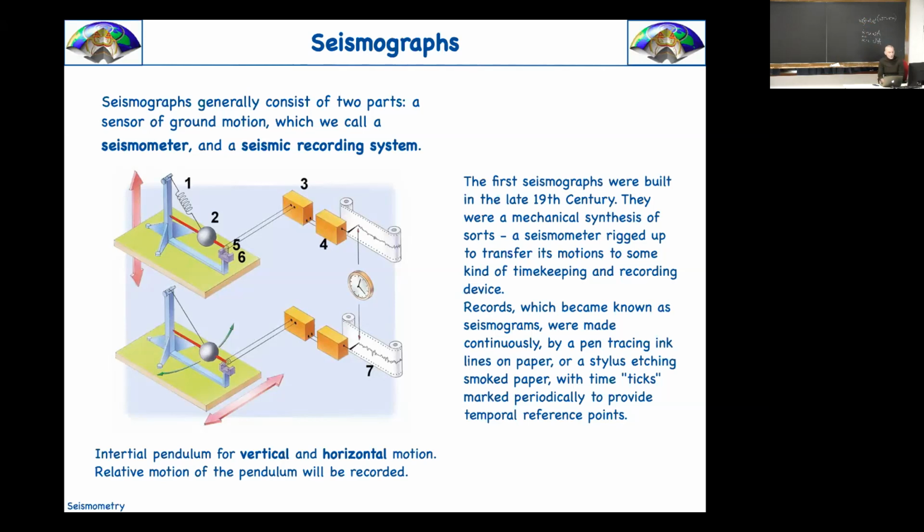And we will see during the next week that high frequencies are more damped than the low ones. So usually acceleration is the domain of the near-source region. That's why accelerometers are usually used for strong motion, whatever it means. It has a classical definition, but if you listen to strong motion seismology, usually they are connected to accelerometers.